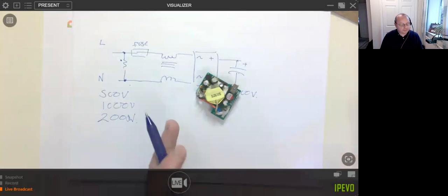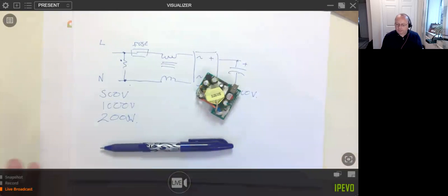It is a fact that whatever you're developing, just because you've got yourself a CE rated or UL rated or TUV or whatever else, just because you've got a component which is rated for the product you're making, it does not give you, I don't know, impunity, the right to just go and say, well, that one's rated, therefore I can get another one that's rated. You just can't do that because all these issues add up.